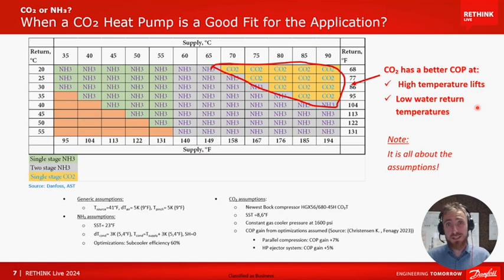I also have to add that our assumptions on the superheat of the evaporator, I believe, are a little bit conservative. They're outdated. They're based on superheat in the range of 18 F in the evaporator. We see that more or less all rack builders on the field, all contractors, they use evaporator superheat of 9 F, but there are some state-of-the-art CO2 manufacturers which can go significantly lower than this, and they can go to a low pinch between evaporator suction SST and ambient air as low as 7 Kelvin, which is 15 F, if I'm not wrong.